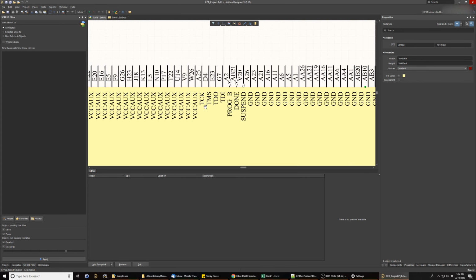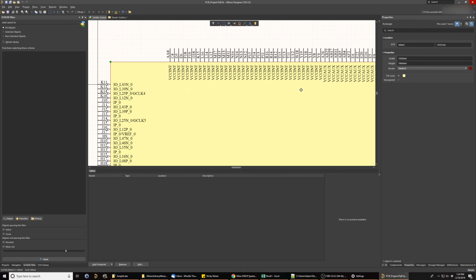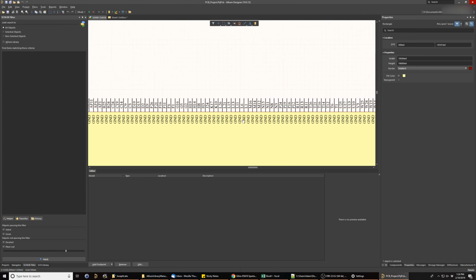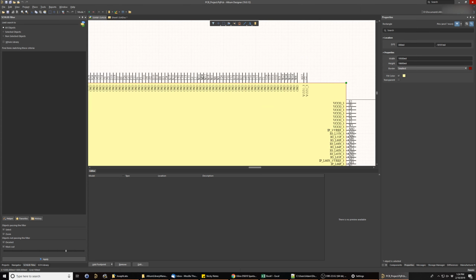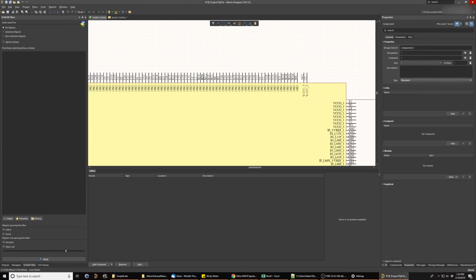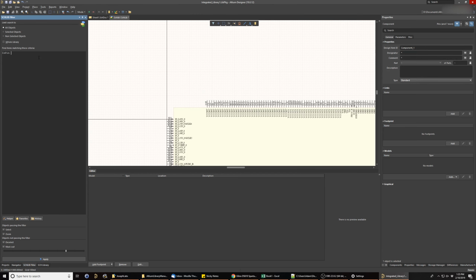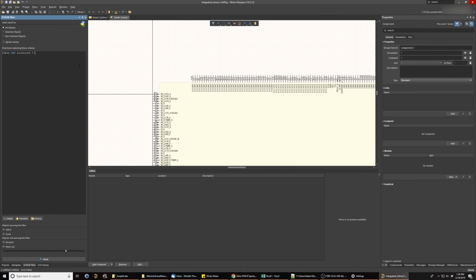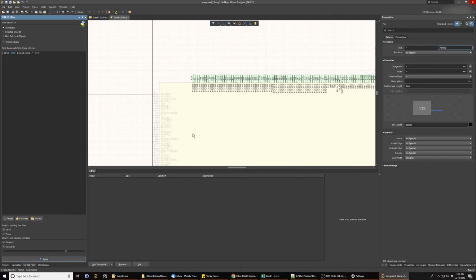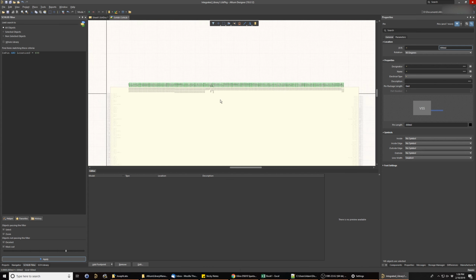open the SCH-lib filter pane. If this is not visible for you, click Panels in the bottom right side of the editor and open it up from there. In the filter window, I type the keyword isPin and paste the relevant X or Y coordinates of each row of pins into the filter. Clicking Apply will apply this filter and select only the pins I want to move.